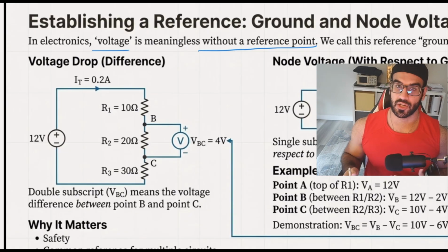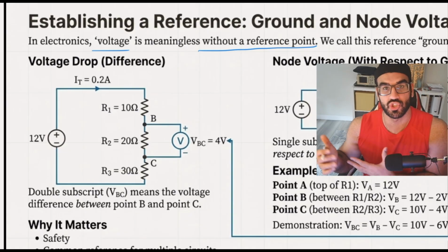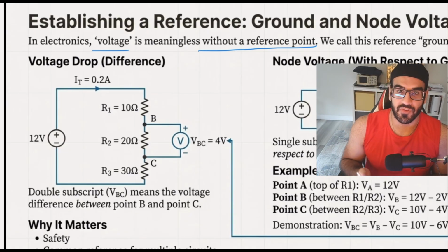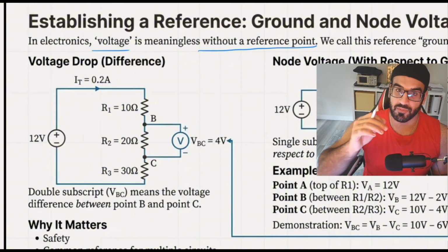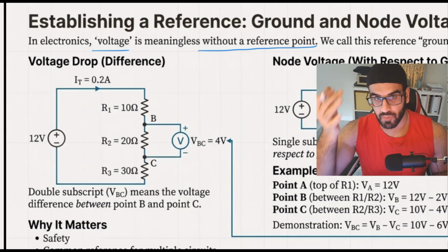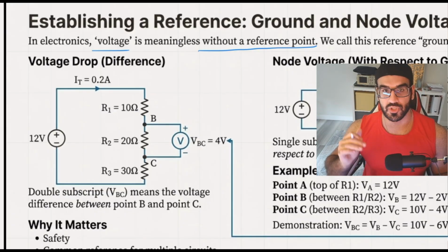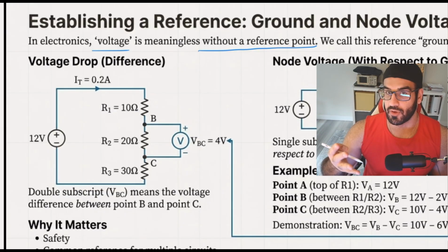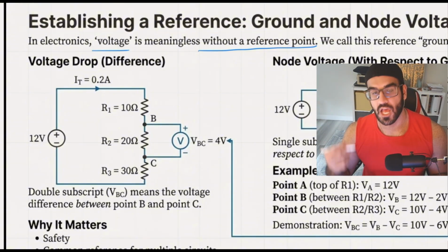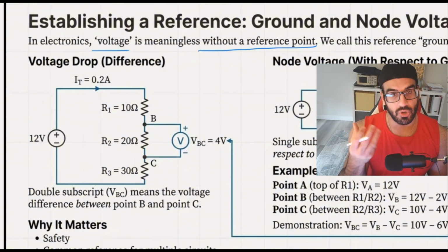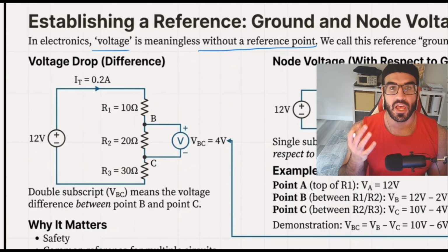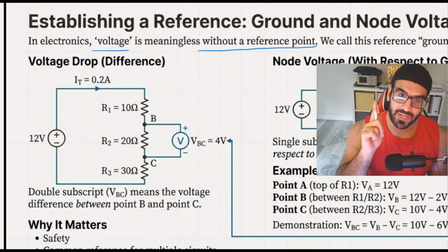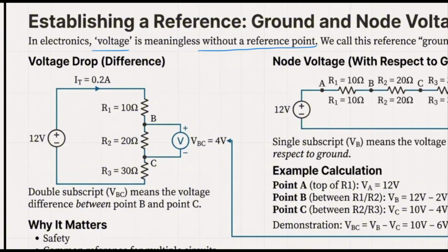So when we are talking about the voltage or voltage drop of a specific component being, for example, 4 volts, it means the difference between the higher part, which we know as positive, and the lower part, which we know as negative, is going to be 4 volt. So again, the voltage, or the right word is voltage difference, is completely meaningless when you're only going to talk about one specific point.